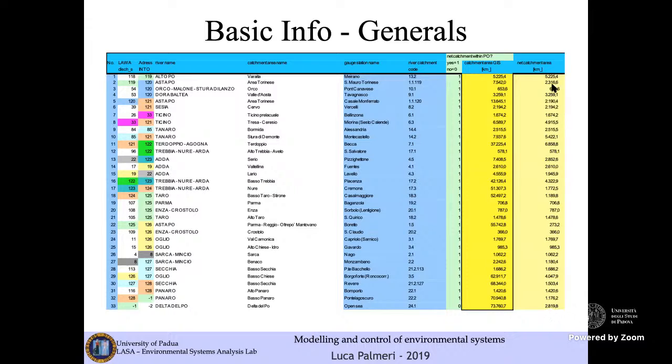If we go on including net catchment to catchment areas, of course, when we arrive at the delta or the discharge Ponte Lago Scuro, the closure of the whole Po catchment, we obtain the figure of more than 73,000 square kilometers, because in Ponte Lago Scuro, all the water that has been passing through the different hydrological subunits arrives at the output of the rivers.